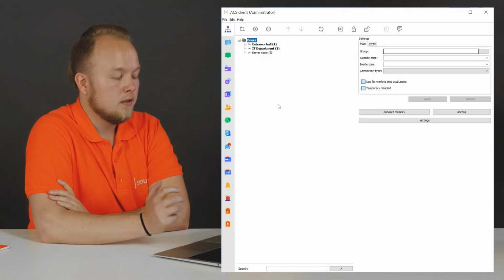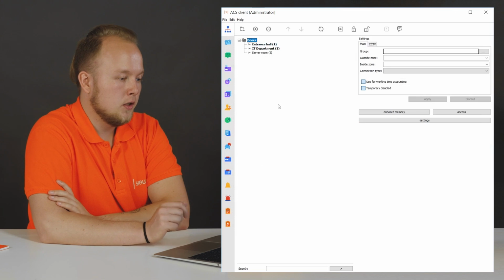Antipanic is a special optional mode of turnstile operation in which it lowers its bars, allowing for maximum throughput of the turnstile. This mode is usually used in emergency situations or for convenient passage with large-sized cargo. Using the Sigur controller, this function can be implemented for the controller to send a command to the turnstile control panel to activate the anti-panic mode.